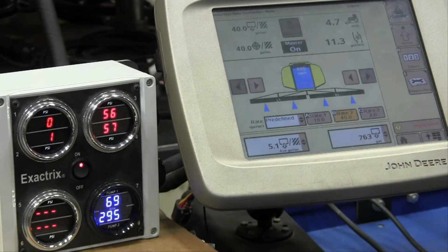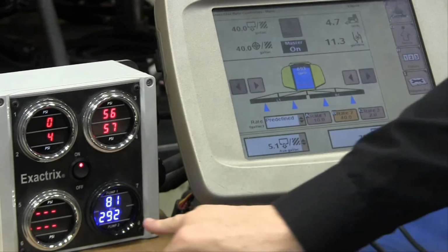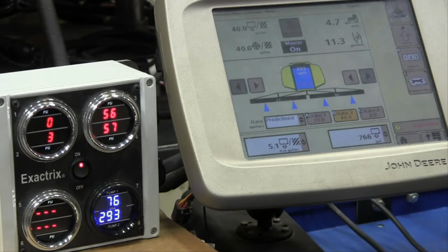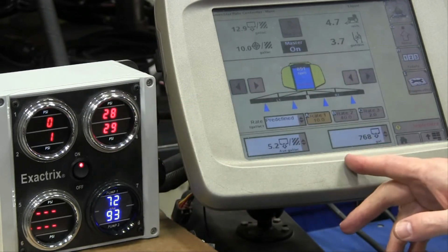Absolutely. From 74. So that's the purpose of PD pumps, it gives you this great readout on the tachometer to reconfirm that not only have you hit the flow target, you've done it with RPM also. Let's go back to 10. When that sucker hits 75, there you go. Still coming down, so it's got a lot of storage in the system. Goes up fast, comes down slow. But the pressure is the key. So let's keep our eyes on the pressure.